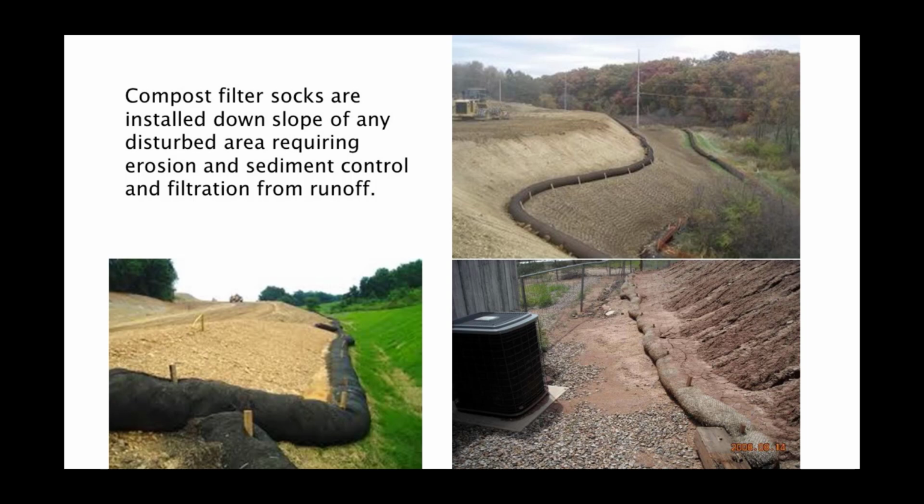On the bottom right-hand side, you'll see a filter sock that has not been properly installed or maintained. The filter sock itself is being overwhelmed by sediment. It's too close to the bottom of the slope, and it has not been maintained properly.